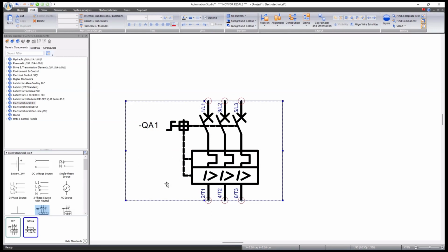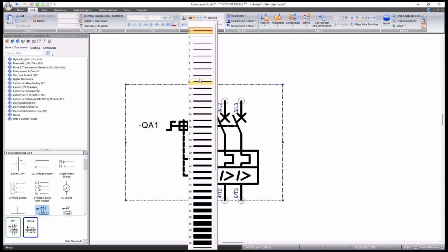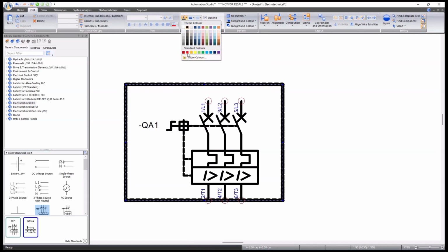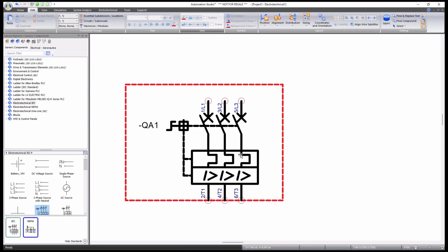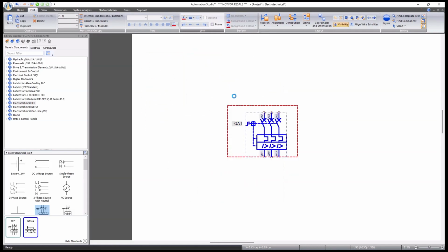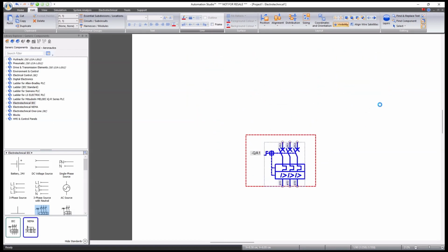So not just on the sides with no port, but even the sides with the port, I can make it a bit larger if I wanted to. I can also change the line type, the line thickness. Sorry, I've actually clicked out there, so I have to go back in, edit frame again. The line thickness and the line color and so on. And then this, maybe that's a bit too thick. This then gets saved with the component. So now if I move the component around, this will get saved with it, or if I create a copy, it also gets saved.